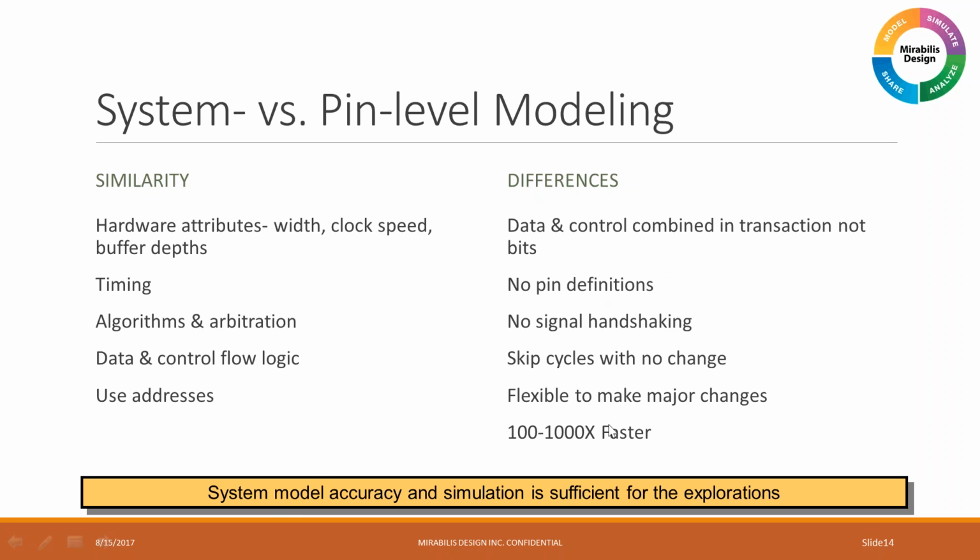And also, even though we run clock by clock, we don't have to incorporate the clocks that are not doing anything. You can still incorporate the power and performance as delays for that time period, but you don't actually incorporate the actual clock itself for those events. As a result of that, you can get up to 1000x faster performance than any of the other mechanisms that you might use for system modeling.